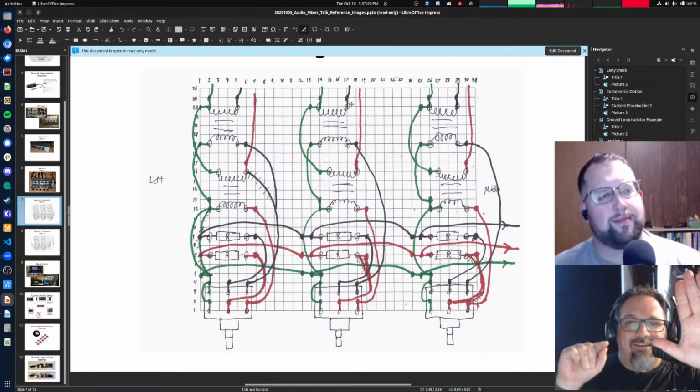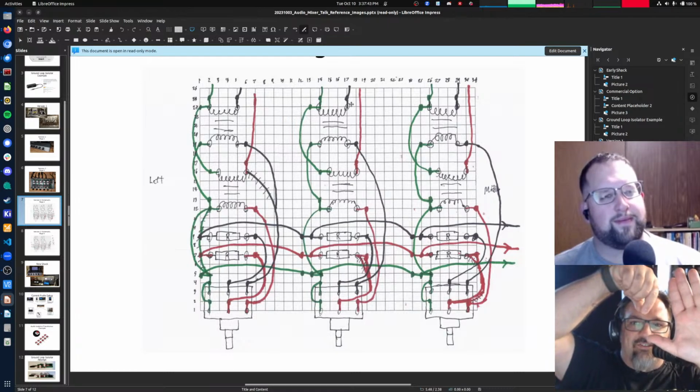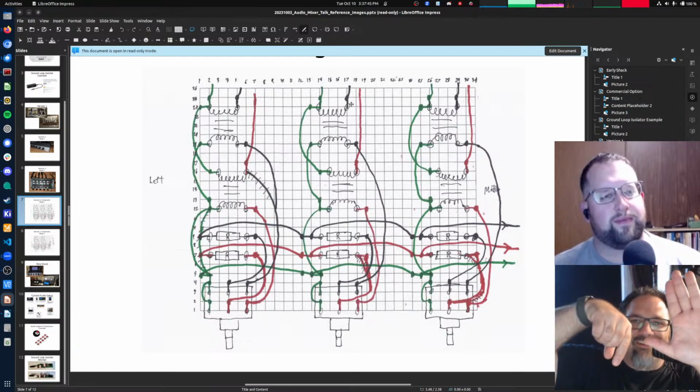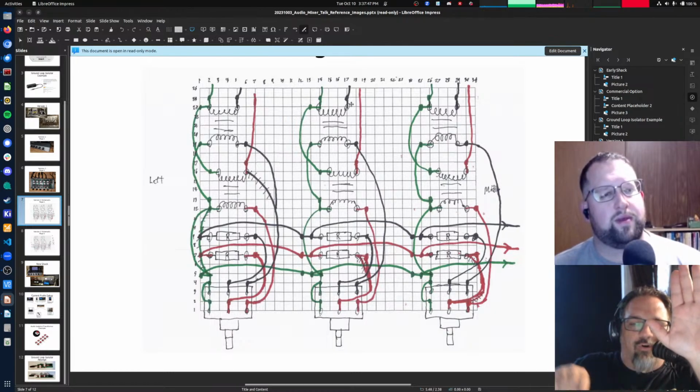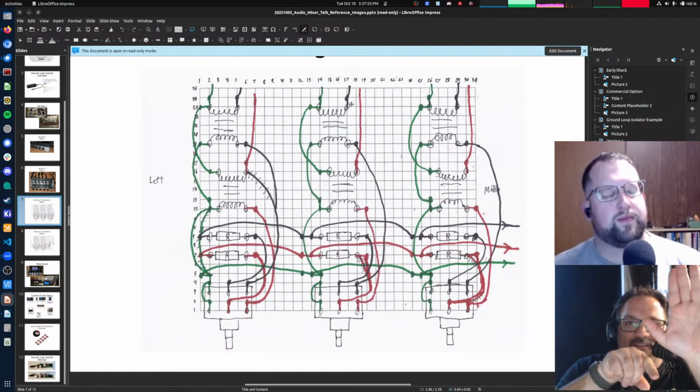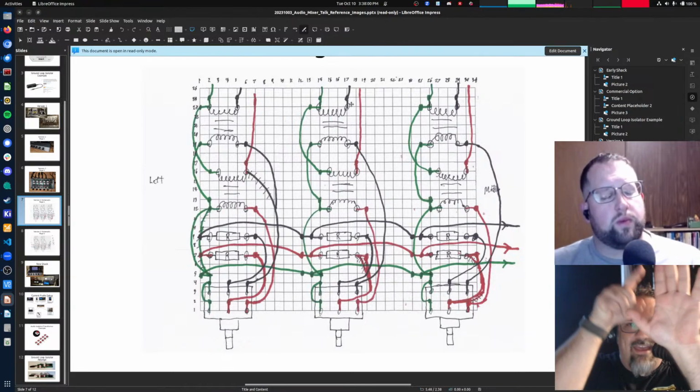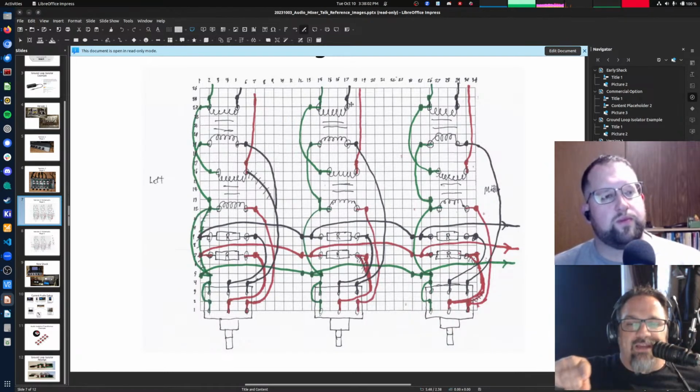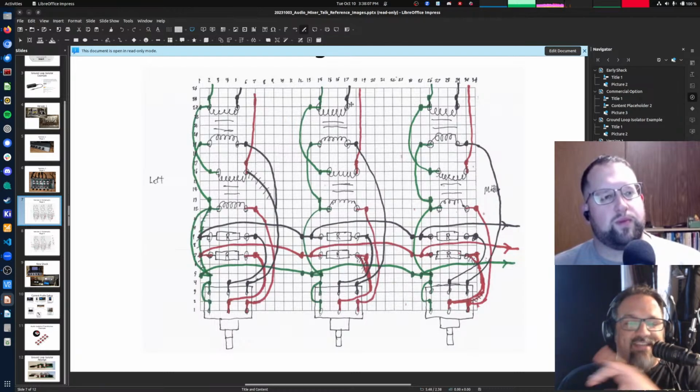So now that connector is connected to the speaker in your Flex. And so even though it has to go through a whole bunch of resistance, it will eventually hit that speaker, go through the impedance of the speaker, and find a ground path. So that back signal has come all the way in through one radio, through your mixer, and back out into the speaker on your Flex. And this is happening on all of your inputs. All your inputs are driving all of the other inputs.